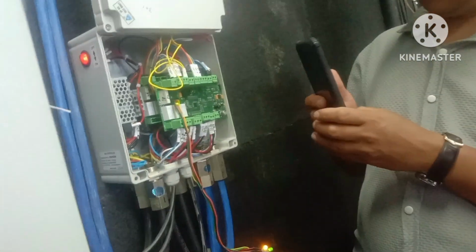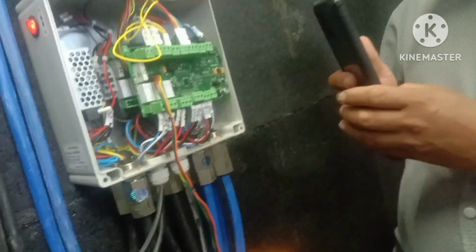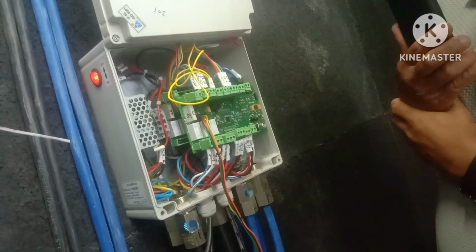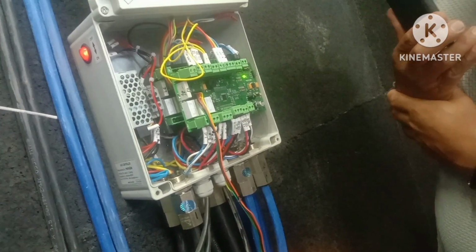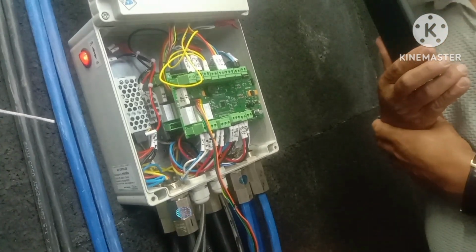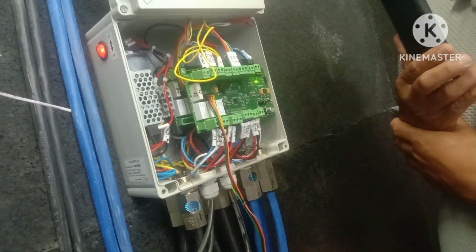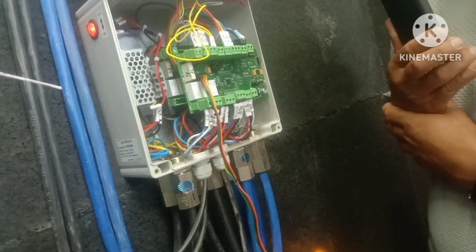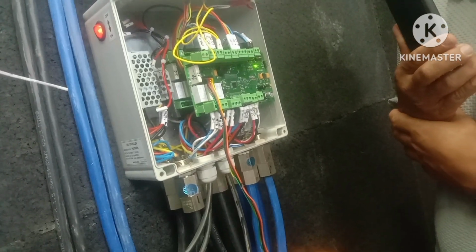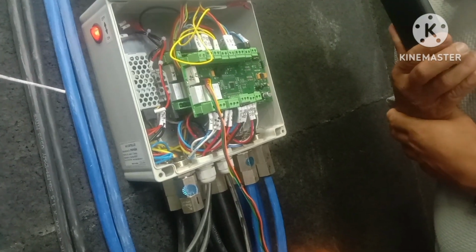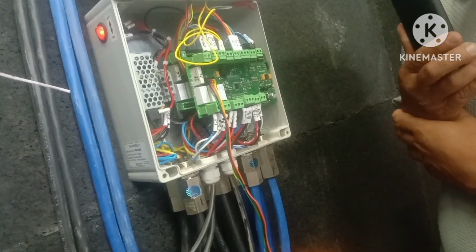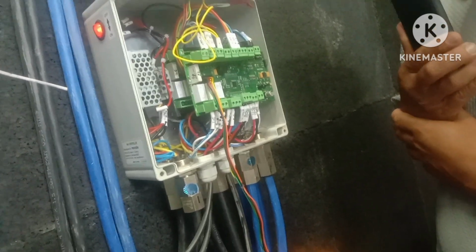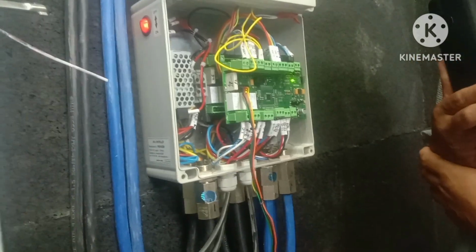Okay, so if you can see, we have the spare controller. When the controller is not working, or some of the IOs which are inbuilt in the controller are not working, how can we test whether it is faulty or not? For that we will have a spare controller. We will open this box carefully, and then connect the same wires at the same points which are attached to the old controller.